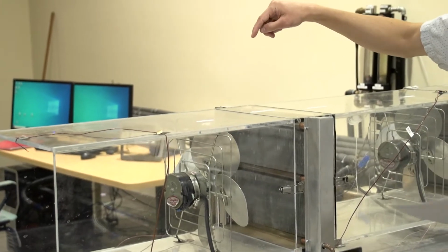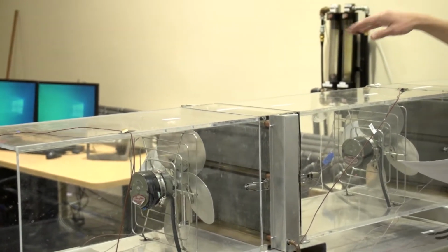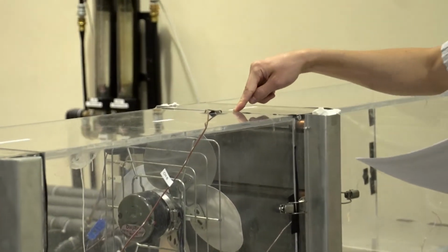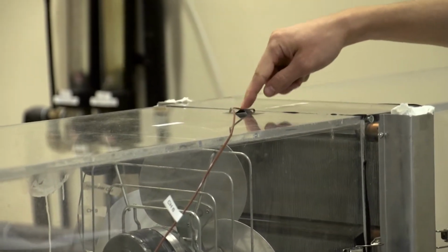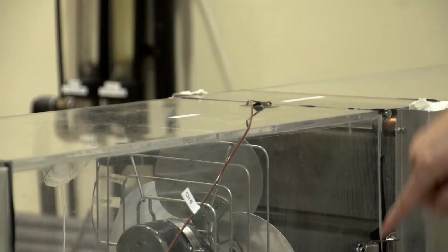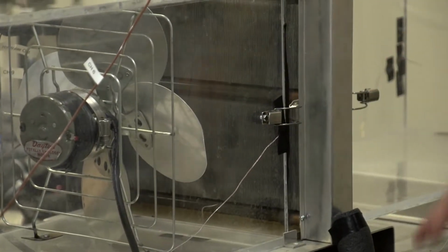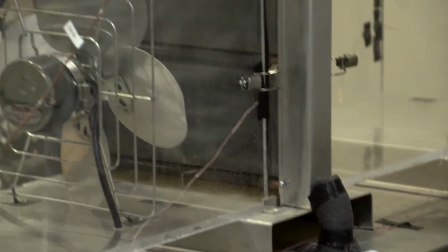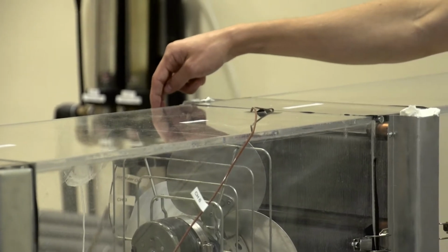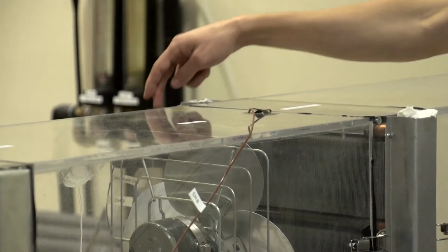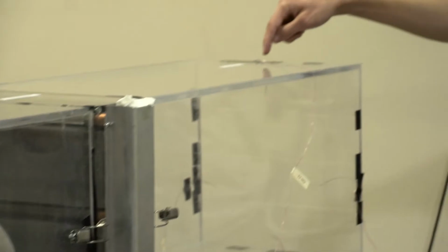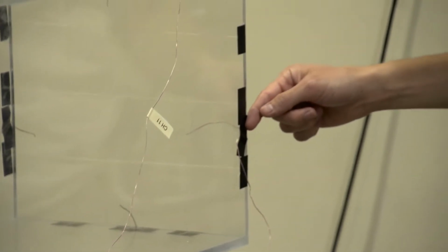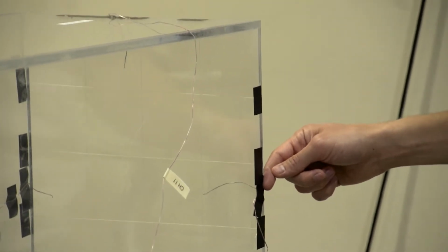You also have, over here, 4 thermocouples to measure the air temperature. 1, 2, 3, 4. You have hot water inlet temperature, again in the enclosure. Hot water outlet temperature, again visible outside the enclosure. And then finally, you have 4 thermocouples here at each side of the tunnel measuring the air outlet temperature.